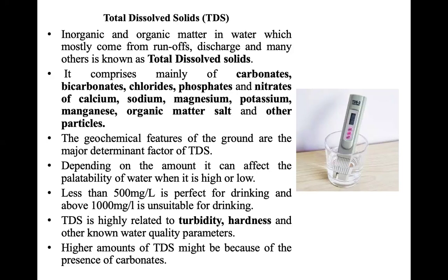And depending on the amount that is present, they can affect how palatable a given water body is. Normally, they shouldn't exceed 500, and water with TDS of less than 500 is considered perfect for drinking. And those that go very high above 1,000 milligrams per liter are also considered unsafe.